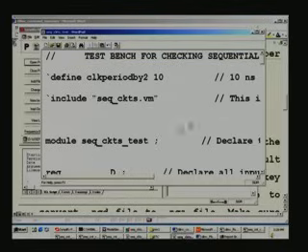In order to see that there is absolutely no difference from the original, we need to invoke ModelSim to see whether this optimized .vm file works. Of course, here this is only a test bench. What is different is that the optimized file is only the design file, but the test bench includes that particular file.